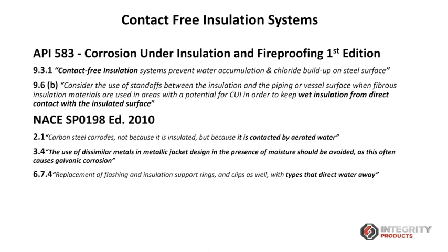Okay, perfect. Thank you. So I just mentioned the word contact-free insulation system while I was talking about the testing of the drain plugs. So what is contact-free insulation and why do we need that? Recalling API 583 first edition, it says that contact-free insulation systems prevent water accumulation and chloride buildup on the steel surface. So that means it's a good thing to have the contact-free insulation system.